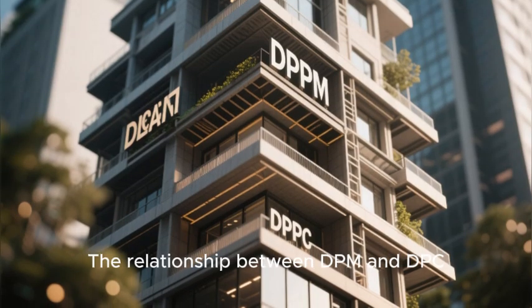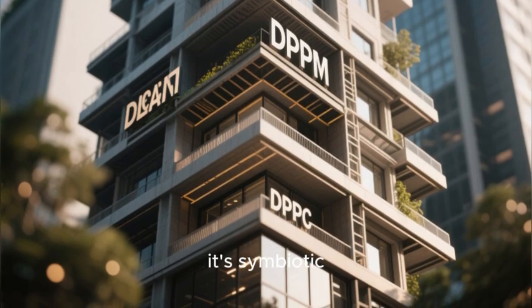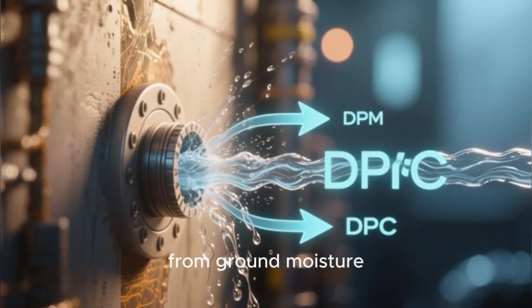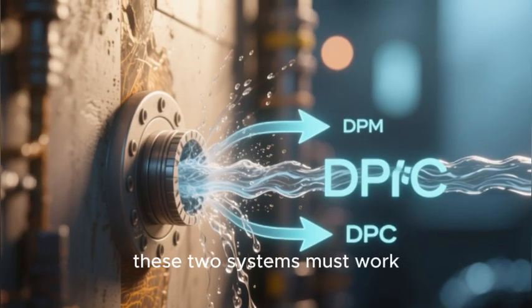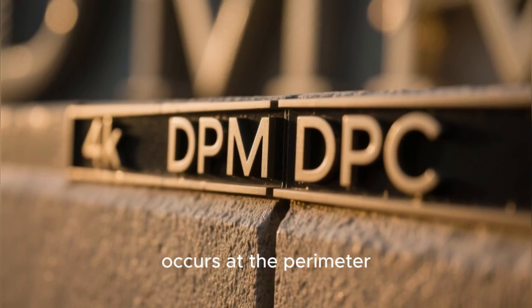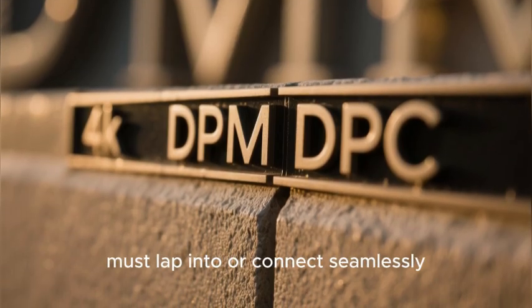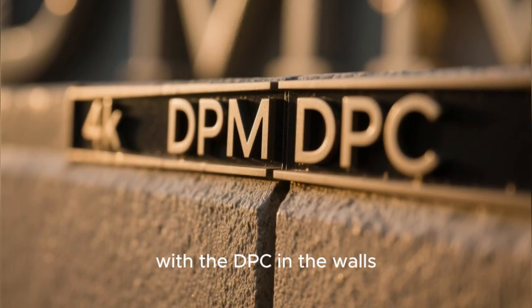The relationship between DPM and DPC isn't just complementary, it's symbiotic. For a building to be truly protected from ground moisture, these two systems must work together as a unified whole. The critical connection occurs at the perimeter, where the DPM, turned up at the edges, must lap into or connect seamlessly with the DPC in the walls.